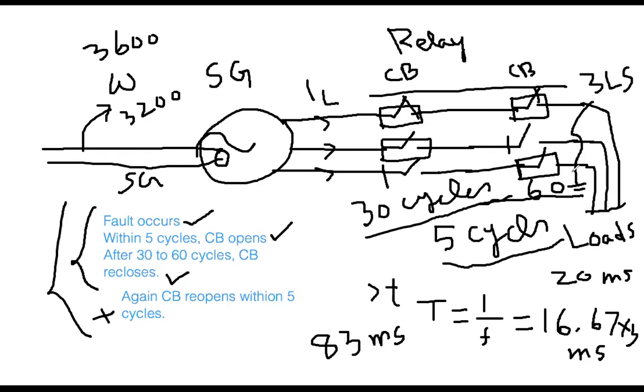But again, if it is a permanent fault, in the case of the tree, it will try to reopen. If MLGW attempts this 3 times, after that they understand that something really bad happened. Then they find where the fault is, go physically, remove the tree or whatever the source of the fault is, and then they fix it.